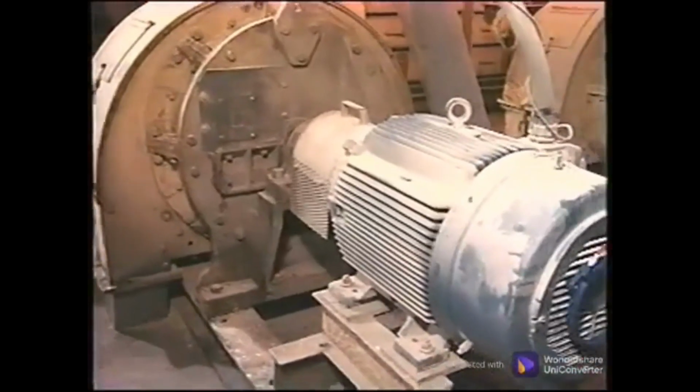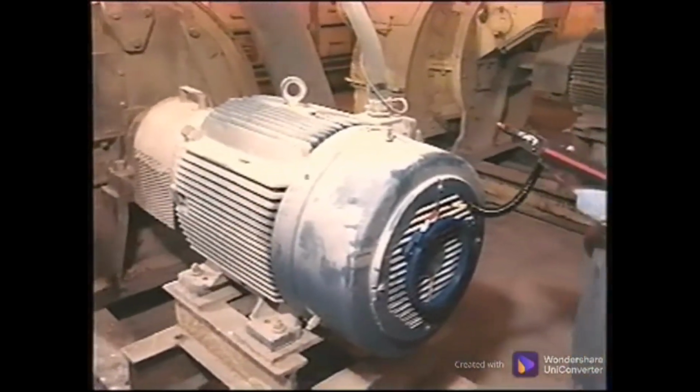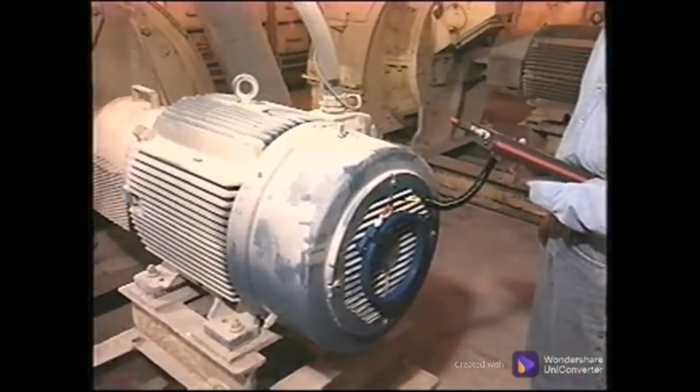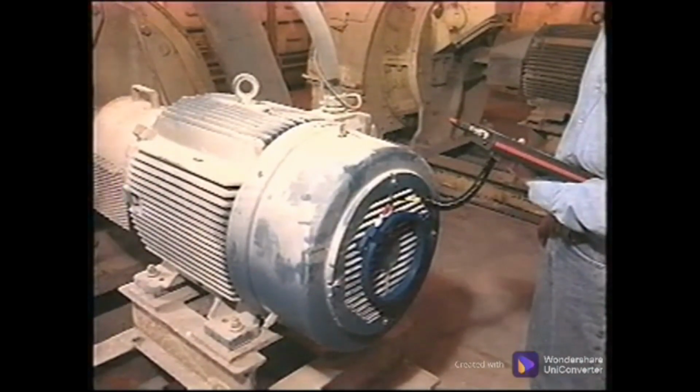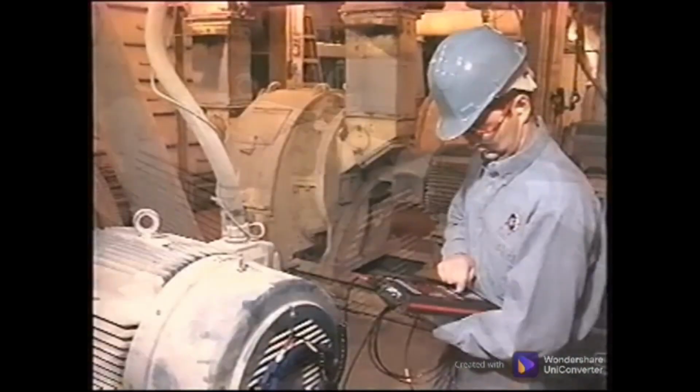A growing technology uses a flux coil to capitalize on the flux field the motor generates while it is running. Since the uniformity of the flux field is directly related to the electrical condition of the motor, a spectrum of the flux can be used to detect problems in the rotor and the stator. There are benefits to flux data. It can be collected on a routine basis along with vibration data because no additional personnel such as an electrician are needed for opening cabinets.